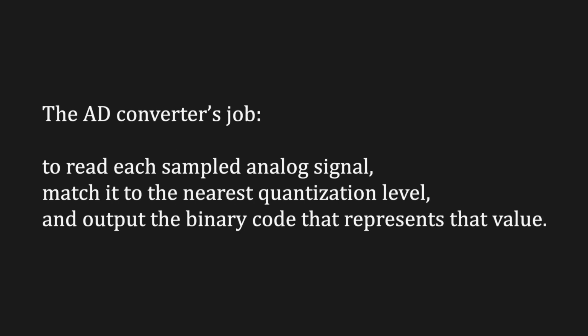The AD converter's job is to read each sampled analog signal, match it to the nearest quantization level, and output the binary code that represents that value. It must do this for every sample quickly and precisely.